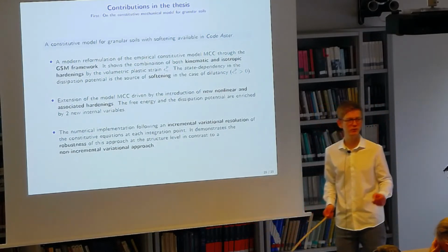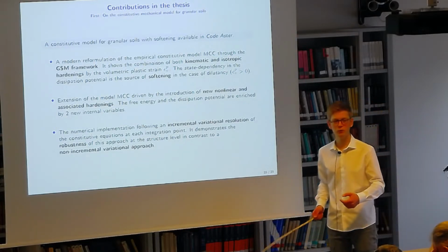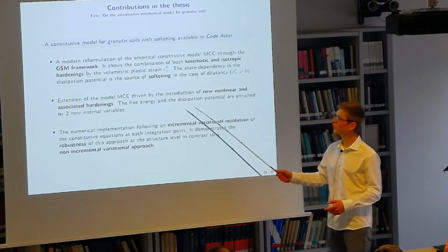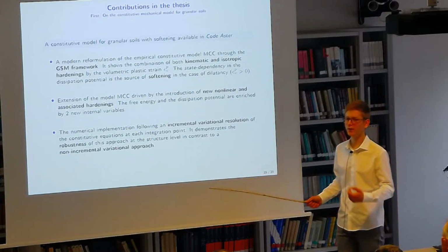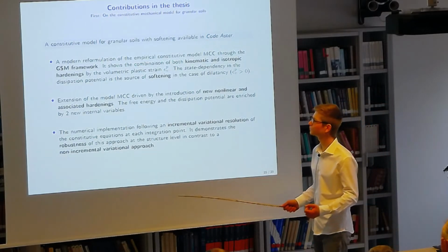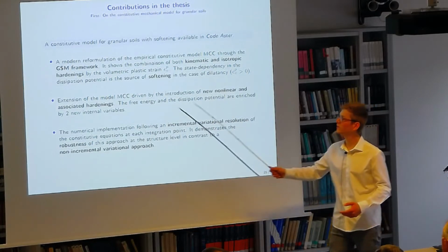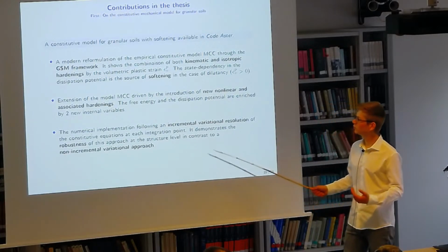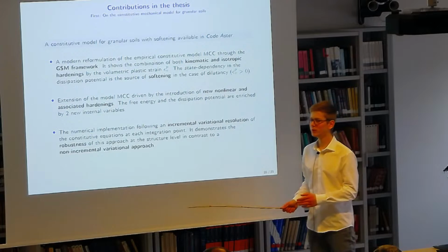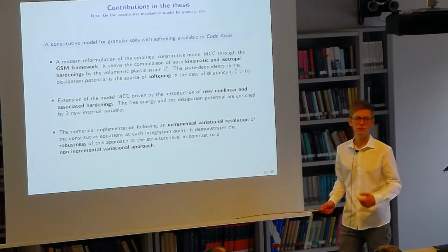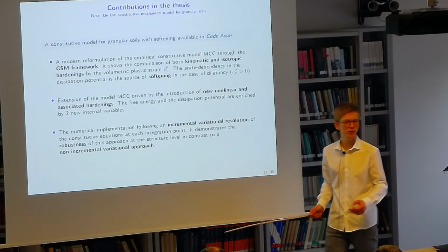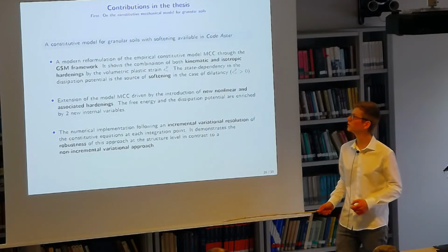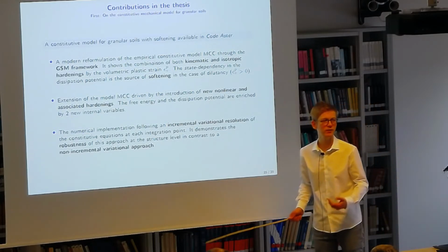However, in order to improve its predictive capabilities for hysteretic behavior and for the softening of dense granular soils, we propose an extension which is based on nonlinear hardenings, which are associated and consistent with the normality of the flow rule. By this formulation and this extension, we have been able to propose a resolution based on an incremental variational one, which all along the numerical experiments in this thesis allowed us to have far better robustness in comparison with a non-variational approach, which is sometimes advanced in order to solve the constitutive equations of the model with state dependency in the dissipation potential.